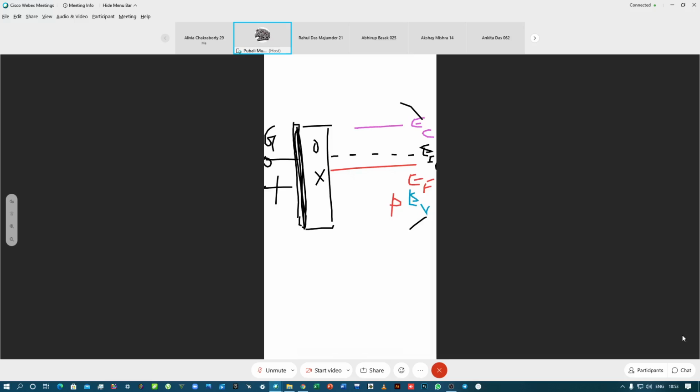In the bulk semiconductor, EC is as it was before, but as you move close to the oxide-metal interface, there is a tendency of EC to move closer to the extrinsic Fermi energy level, because there is a larger number of electrons over there. And since the material is becoming less p-type, the valence band has a tendency of moving away from the extrinsic Fermi energy level at the oxide semiconductor interface.